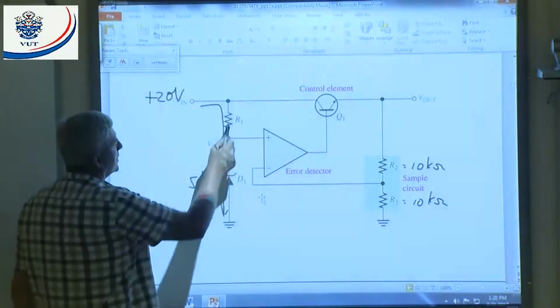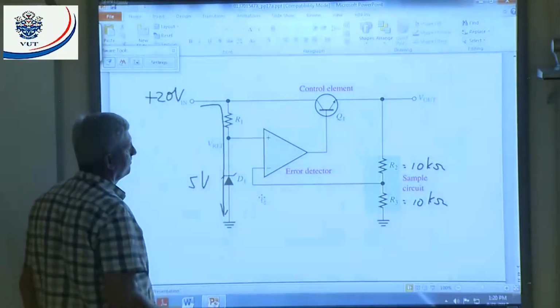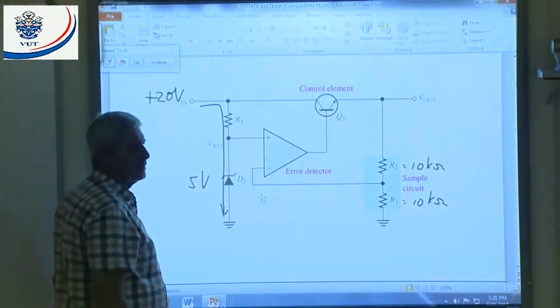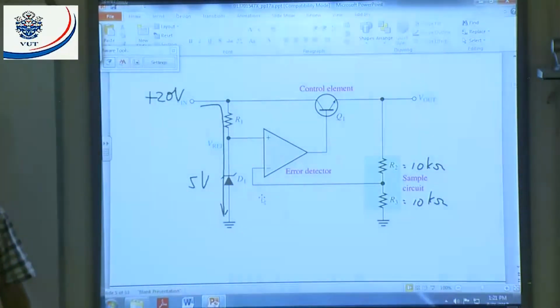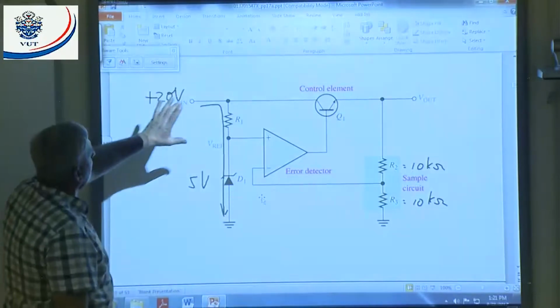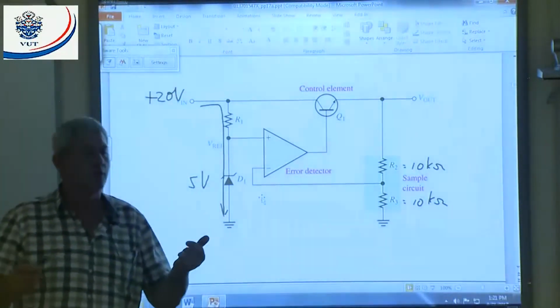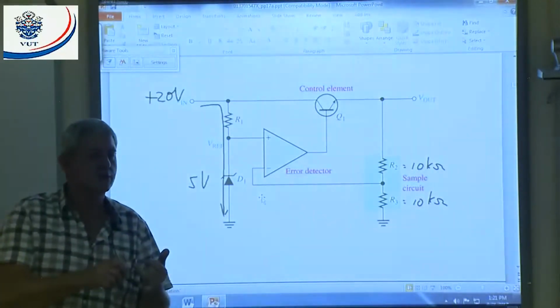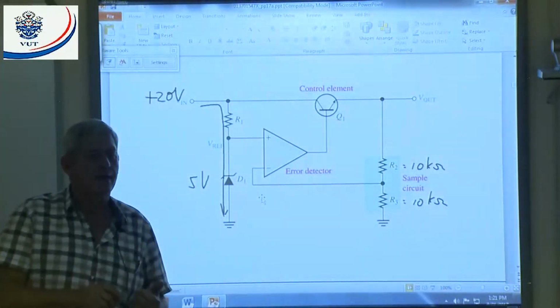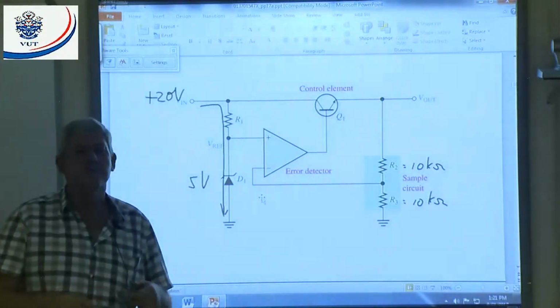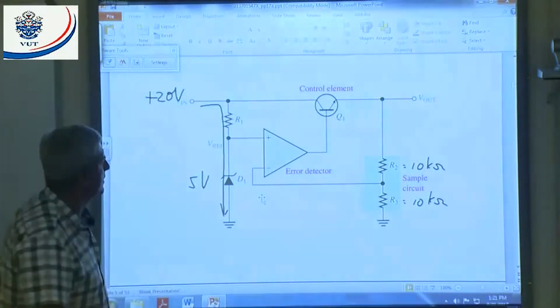If there's 20 volts, what's going to be across R1? What voltage is going to be across R1? 20. You want me to kill you, eh? Yes, voltage. What will the voltage be across R1? I always tell the students, what must you do? Think about Ohm's law, Kirchhoff's voltage and current law, and Ohm's law. If you can apply those laws, you should always get the right answer.